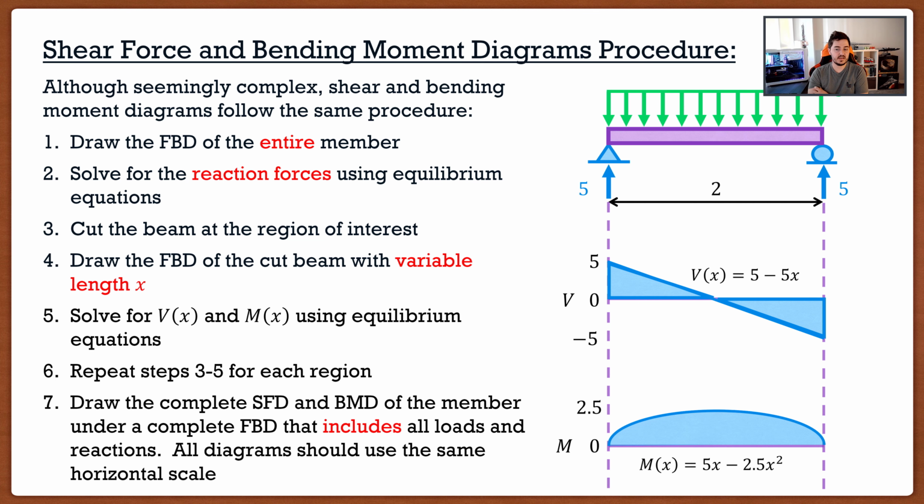Now, if that's the case, and our shear force is the derivative, and we were to take that derivative and set it equal to 0, well, we know that's how we find minimums or maximums. So if we were to look at our shear force and locate the point where it's equal to 0, notice how that's the location of the maximum bending moment. So as we're going to discuss next video, everything here is intertwined.